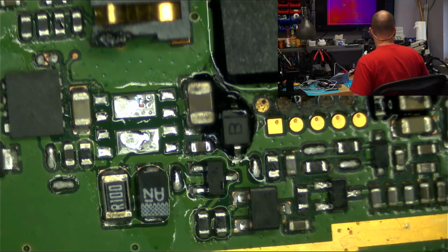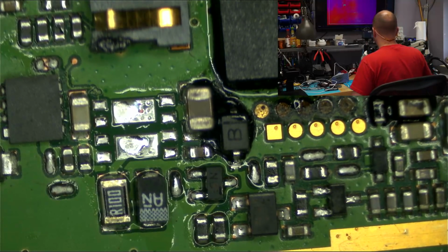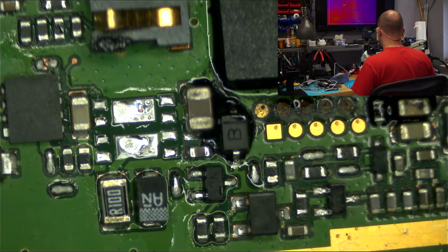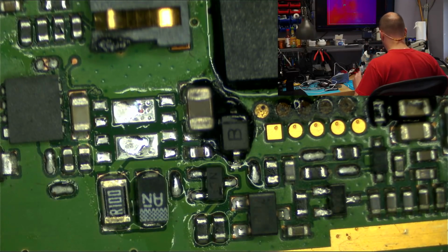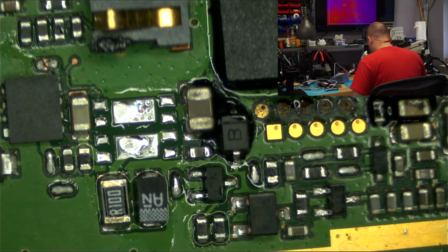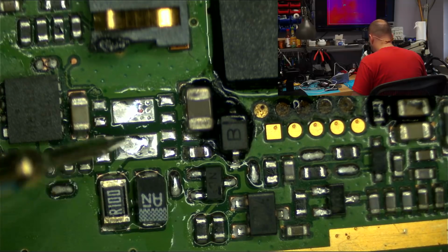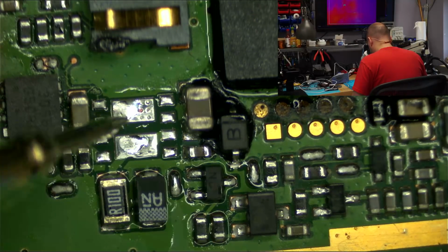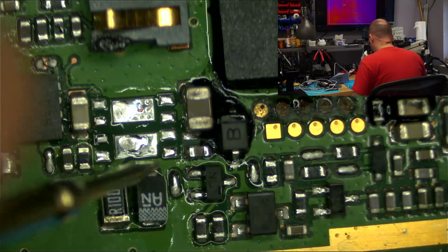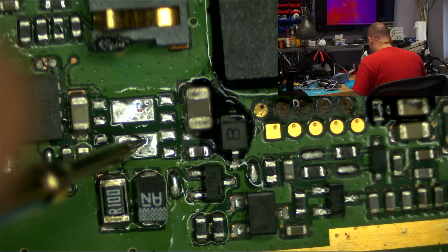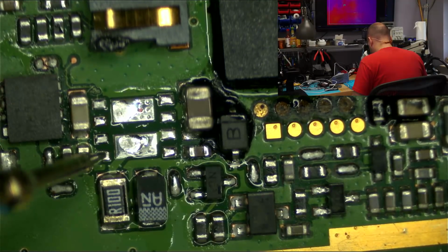Okay, I want to know a little bit more about this board, so let's find which pad on here was ground. Take my multimeter, I'm going to use it in just beep mode. Let's put one on ground, let's see what... This is high voltage. That's not ground. This was ground, yes, this is ground.